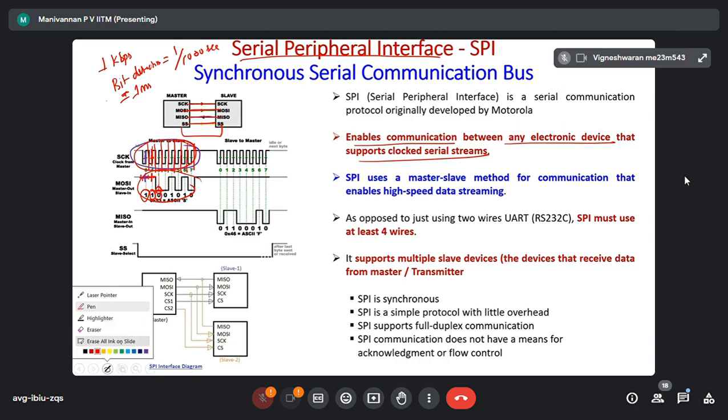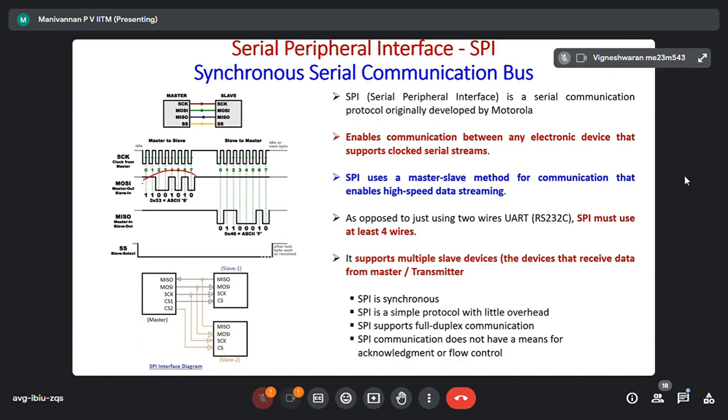Okay. Now another thing: see here, the master is transmitting data to the slave on the green wire. Now the slave is replying. The slave can also give a reply. Please note that the slave can transmit data in SPI also. Then what will happen? That data will come from the MISO pin only. This is the slave reply. It comes to MISO, and the master is going to read. MI means master input, slave output. The data is sent back. So this is how it works.